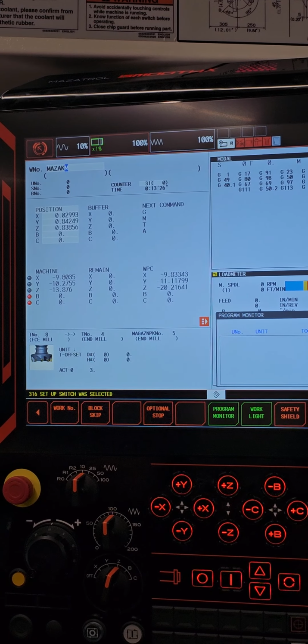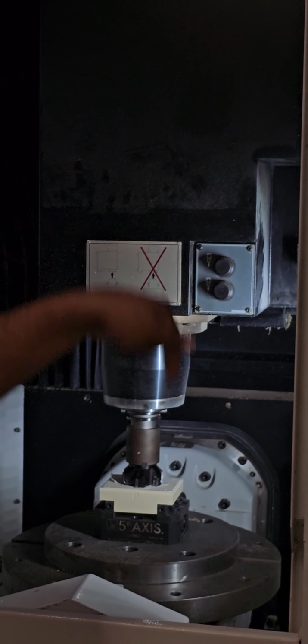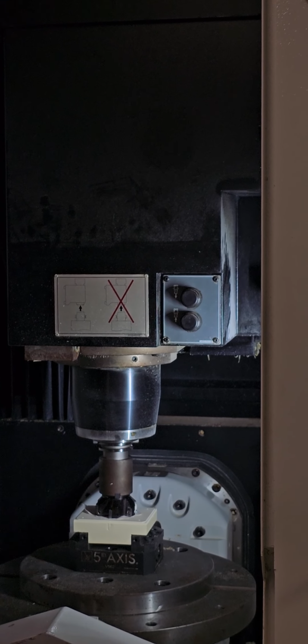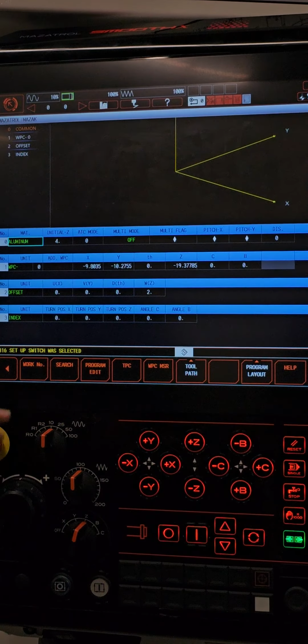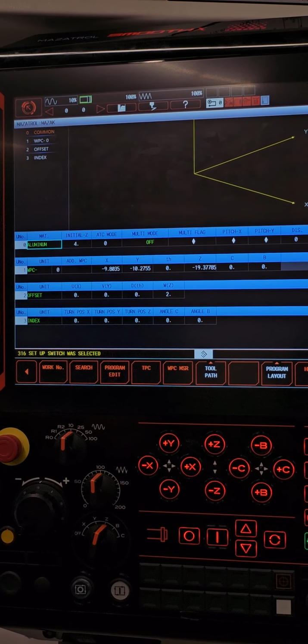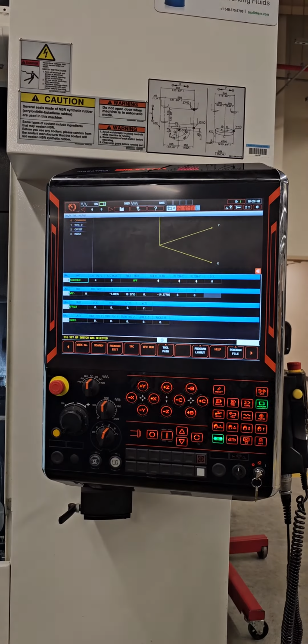So for your test, you're gonna have to touch off your 2 tools, auto and semi. You're gonna have to find your X0, Y0, Z0, right? And then you're gonna have to make your program with those 5 different lines. And that's it. All within 20 minutes.